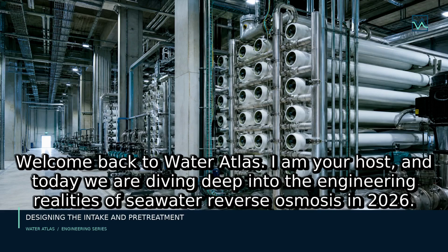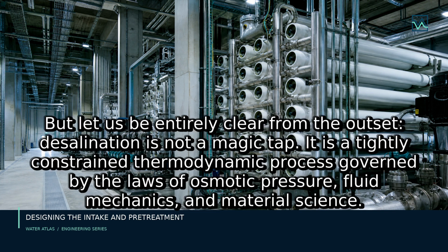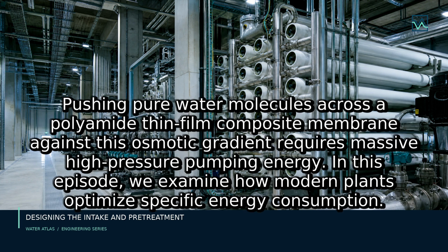When designing a modern seawater reverse osmosis facility, engineers do not simply pump seawater through a membrane rack. They must overcome the natural osmotic pressure of high salinity water, typically around 25 to 30 bar for standard open ocean seawater, and significantly higher in enclosed basins like the Arabian Gulf or the Red Sea. Pushing pure water molecules across a polyamide thin film composite membrane against this osmotic gradient requires massive high-pressure pumping energy.